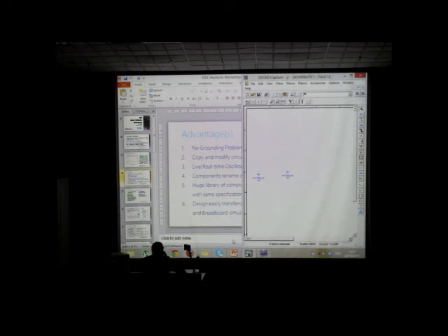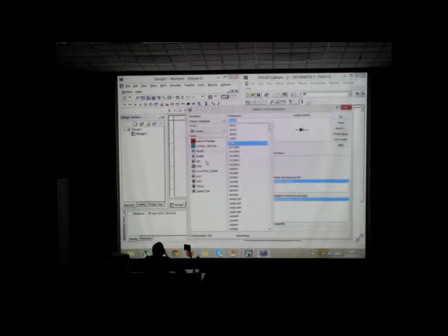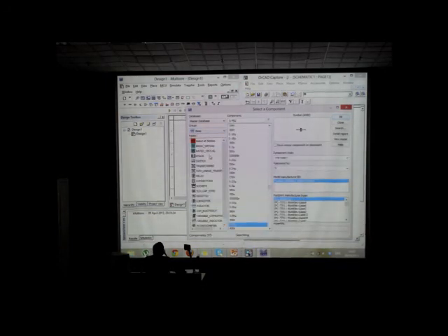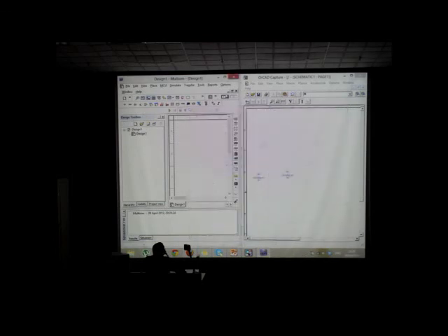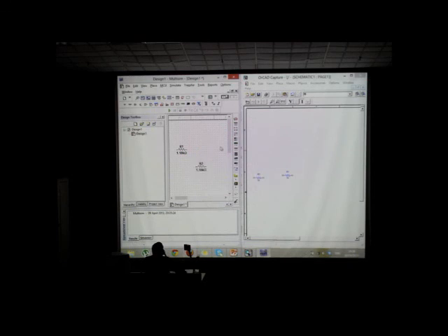But in Multisim, what I saw was, let's just have a resistor. I think it's in Basic, yeah, resistor. When you have a resistor here, it's named R1. When you copy it and paste it, it's R2. It's automatically renamed, it increases. So you don't need to worry about renaming, because sometimes you don't want to go to parts and import another resistor. You just want to copy this resistor and use it in your circuit. This is a very convenient thing in Multisim. In PSpice, you can't do that, and then it will cause problems.